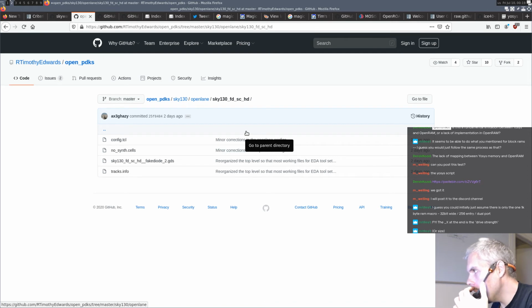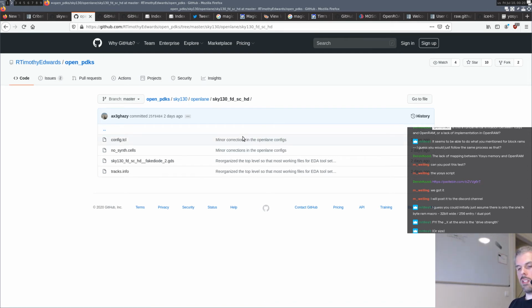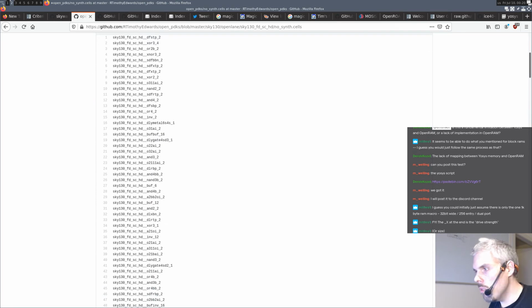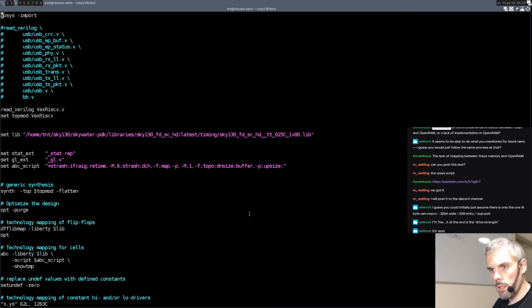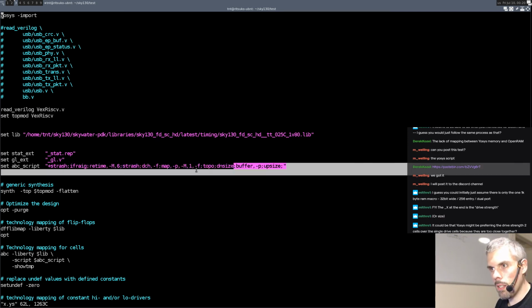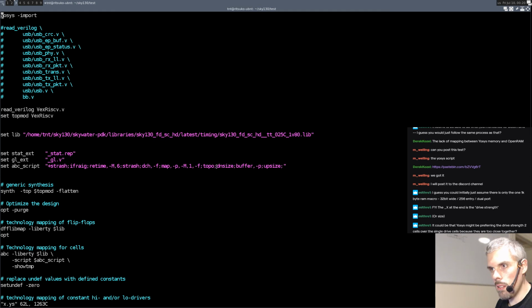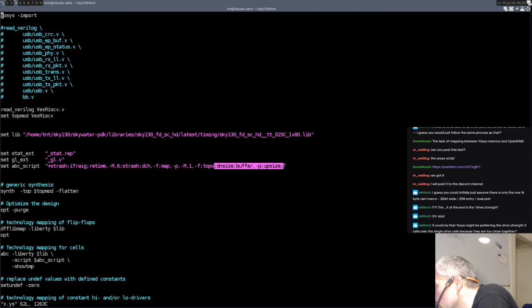Yeah, I know that there are the variants with several output buffer transistors to drive bigger nets and stuff like that. But that's my question: why? Because as far as I know, in the synthesis script, so if I understood correctly, it knows the size, and so they have this special pass called downsize, buffer, upsize, which should, depending on the fanout, automatically bump the drive strength.